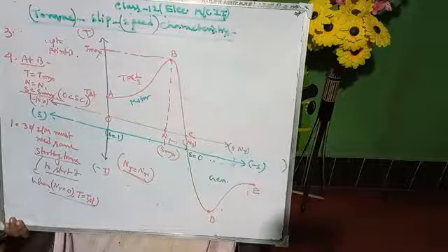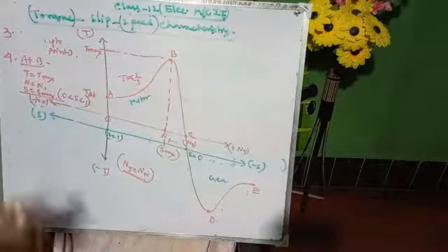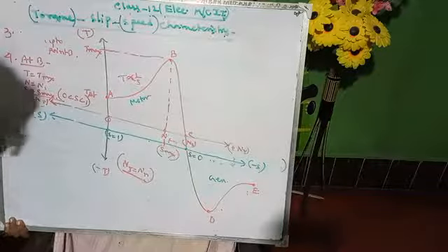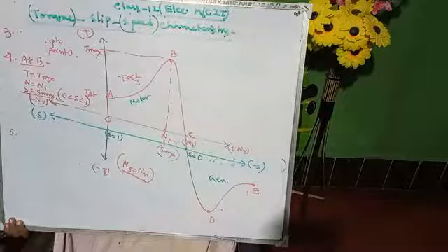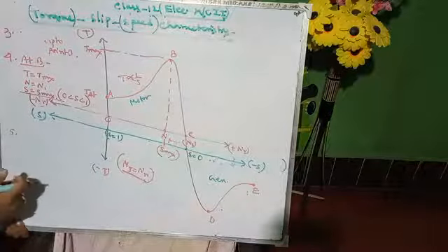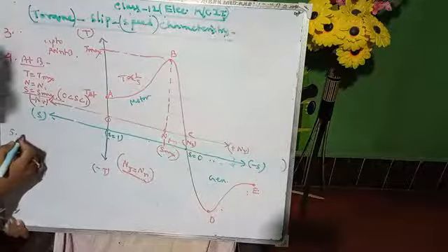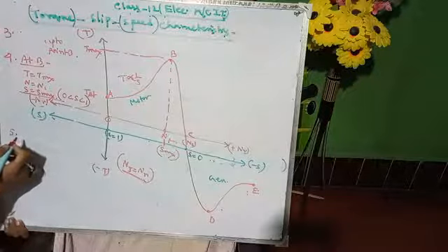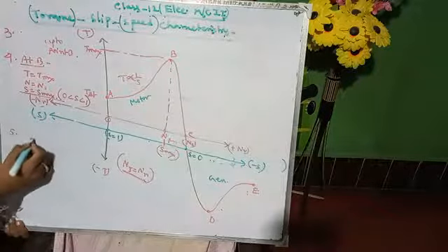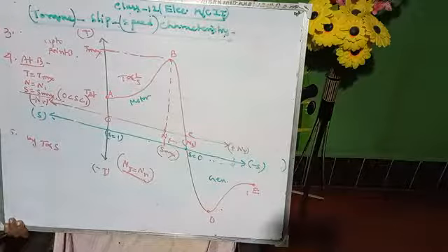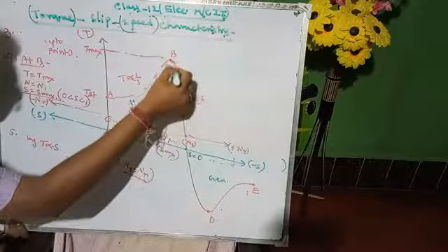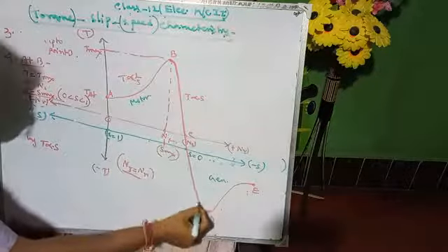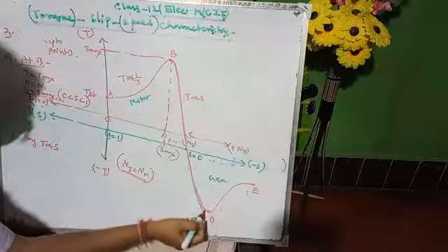Now move to the fifth point. Again, by increasing the speed, the torque will fall to 0, represented by point C, by T being proportional to minus S. It is linear up to this much.